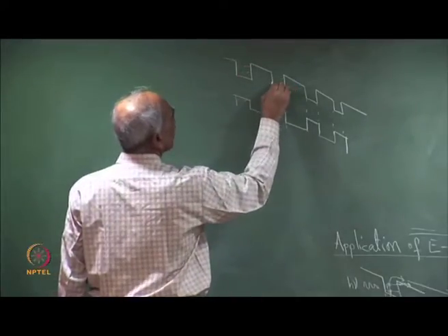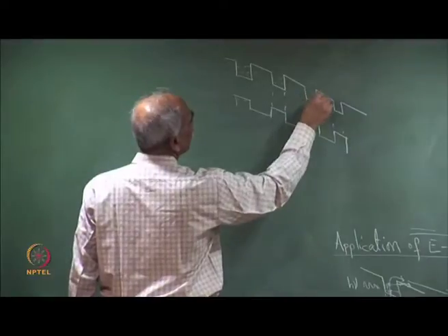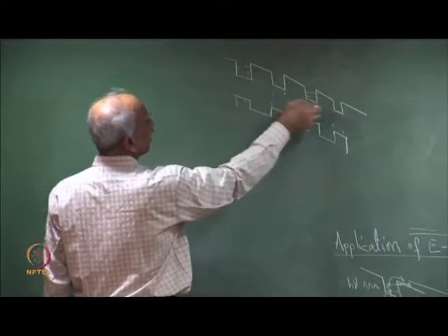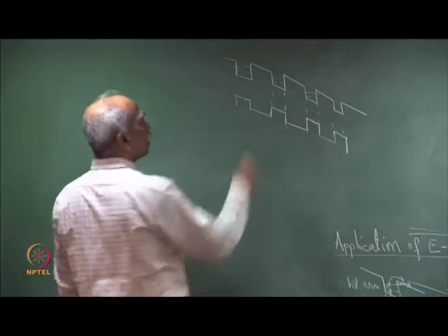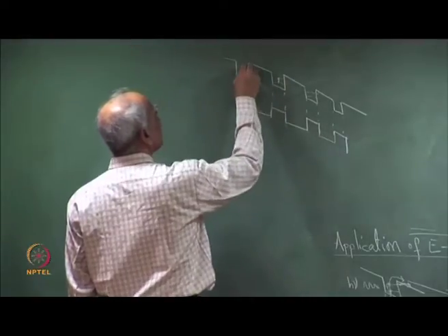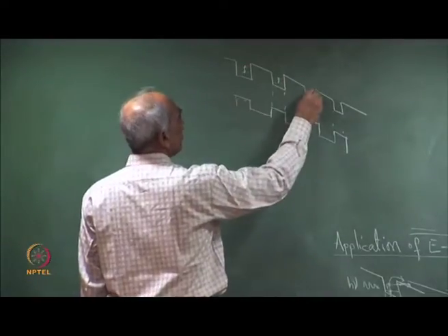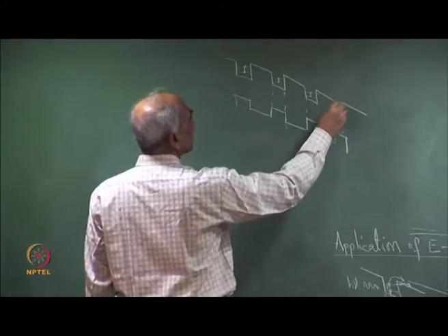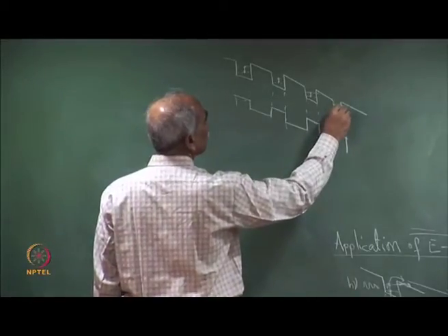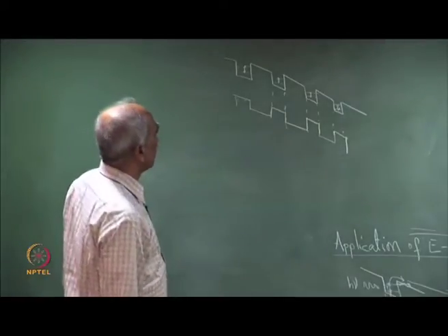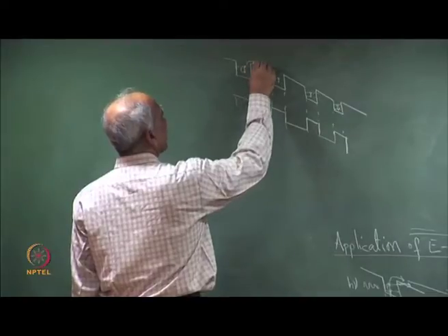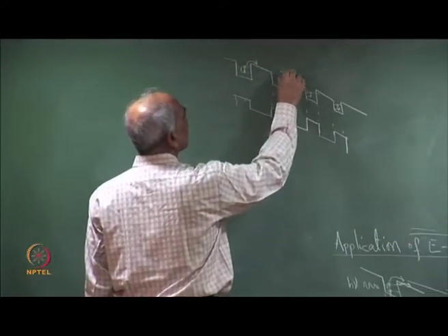In each of the wells we have the same energy difference, provided they are identical. If the well width is the same everywhere, then the energy separation between the two subband levels is the same everywhere, and therefore photons of the same energy can be absorbed. So, the electron makes an upward transition and then a transition outward.